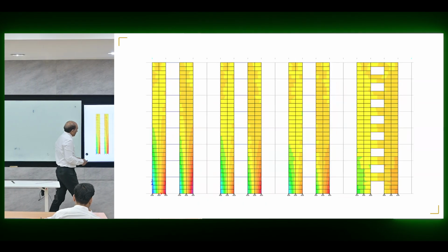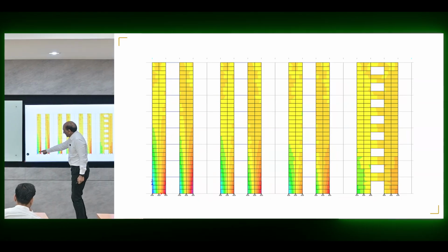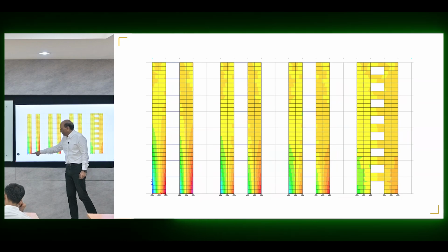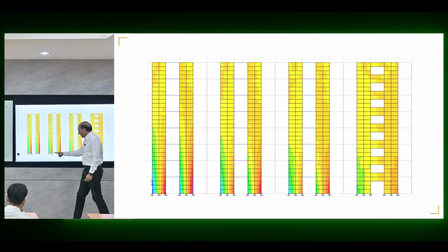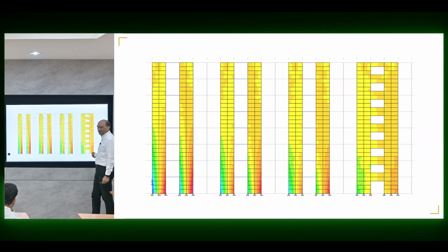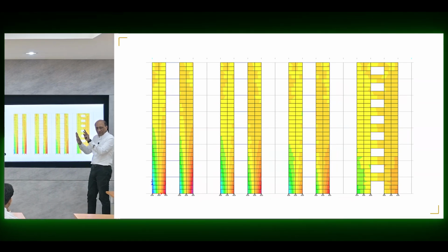And then you can see now tension, compression. These 2 walls are bending independently as 2 separate walls. So each one of them is pure bending moment. Therefore, gradually, you see tension and compression shifted to the extreme edges, because of the shear transfer between them, they start to act as one big element.